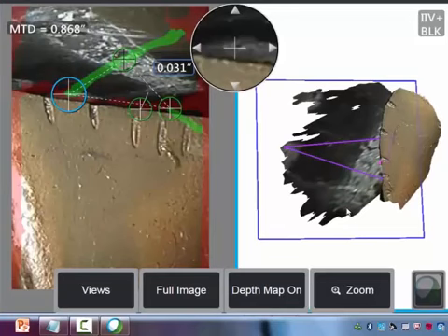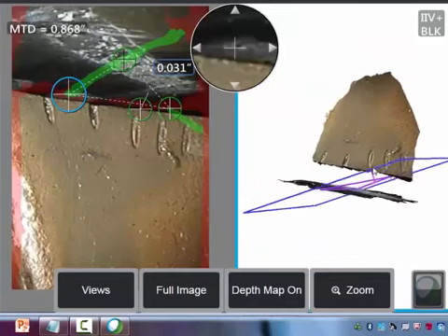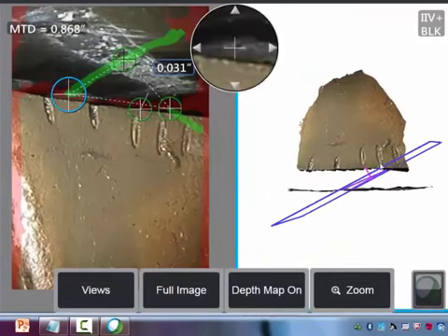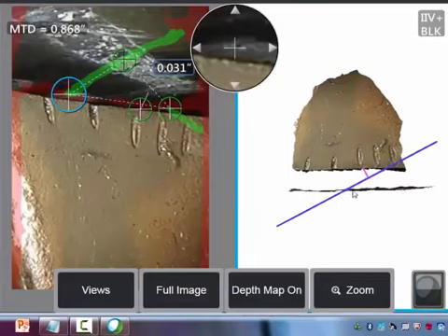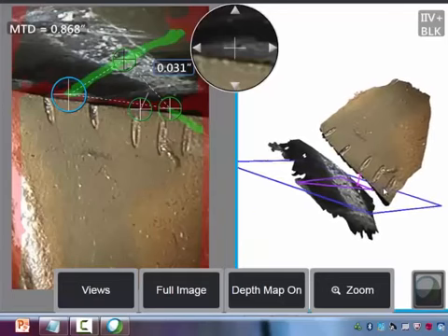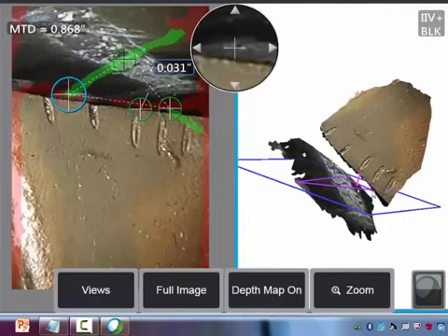As we rotate the point cloud, we quickly notice that our reference plane, which should be aligned with the shroud data, is actually tilted. That's being caused by one of our cursors, which in 3D space, where the measurement is actually made, is sitting up here near the edge of the blade rather than down on the shroud where we would expect it to be.